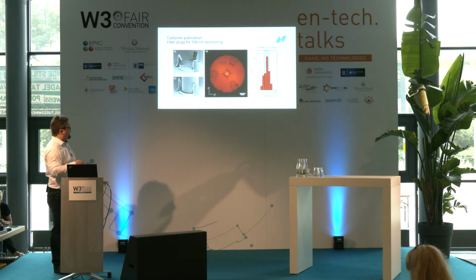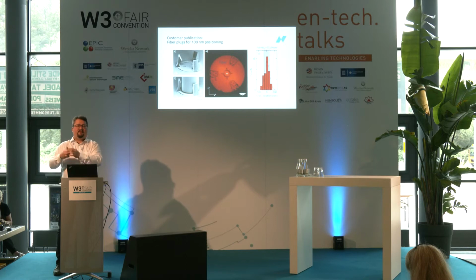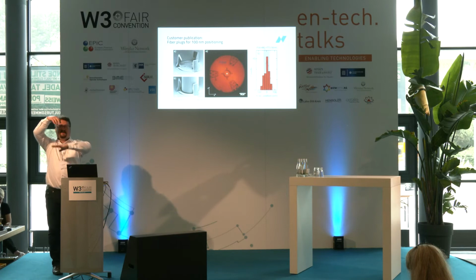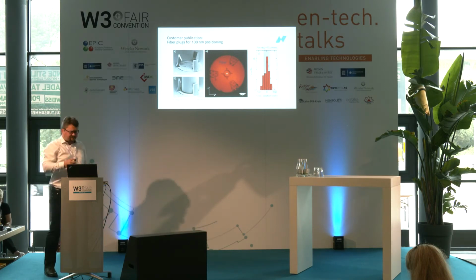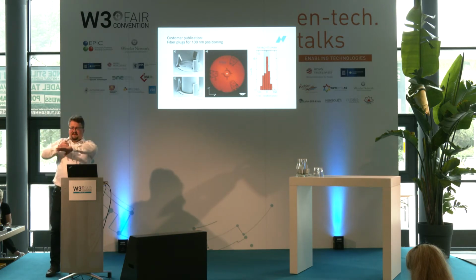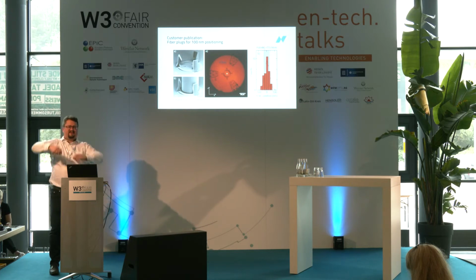For example, this publication from 2018 from one of our customers: they have a chip on which they have some photonic components, some photonic waveguides, and they want to couple light into this chip from a fiber optical cable. And this fiber optical cable, from the way that the experiment is built, has to come in from the top. And if it's placed with a sufficiently high precision onto this chip, they have some kind of a grating that then diffracts the light to the side and couples it into the waveguide. But it's not trivial to align this fiber to the system on the chip.